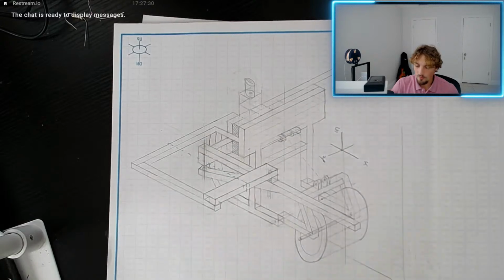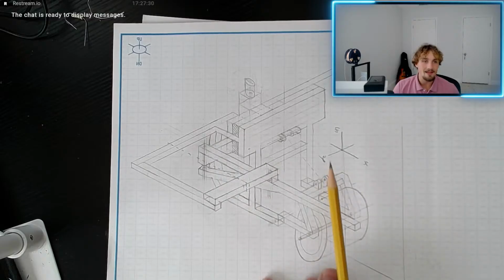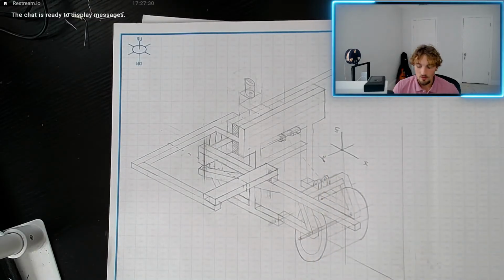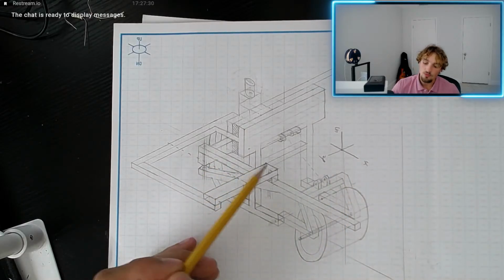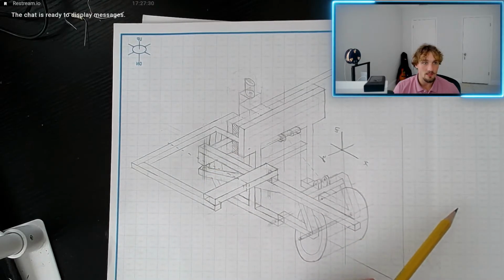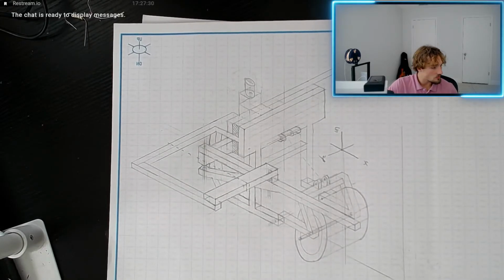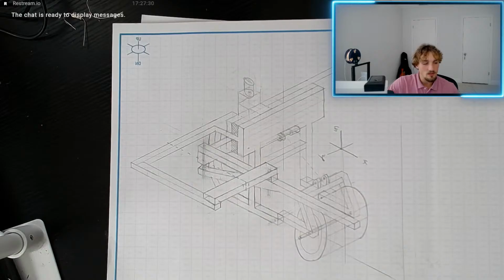But regardless, we've defined our axes. So the big question is looking at the z-axis. The y-axis is where we're going to produce some torque, or rather a moment, due to our asymmetrical mass along the x-axis, right? We have a little more mass over here, and less on this side. This is going to cause a moment, this is going to cause torque. These are factors that we need to take into account when we're doing this build, because this is going to contribute.